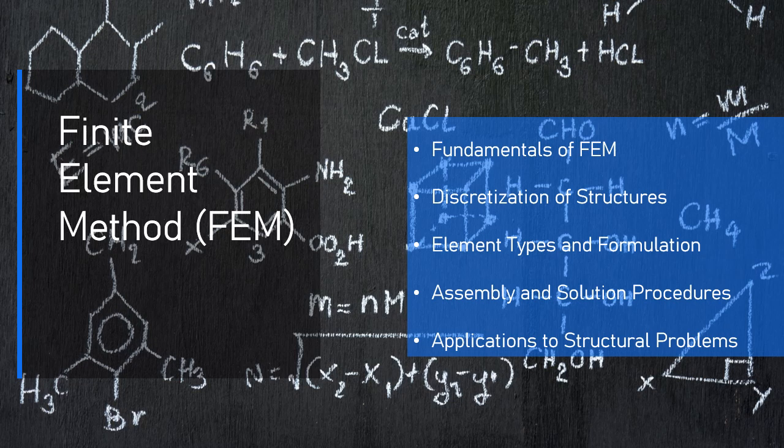4.4. Types of meshes. The mesh plays a crucial role in determining the accuracy of the solution. There are several types of meshes, which can be classified based on the element shape or the mesh refinement. 1. Structured mesh. A structured mesh is created by dividing the domain into a grid of elements that follow a regular pattern, like rows and columns.